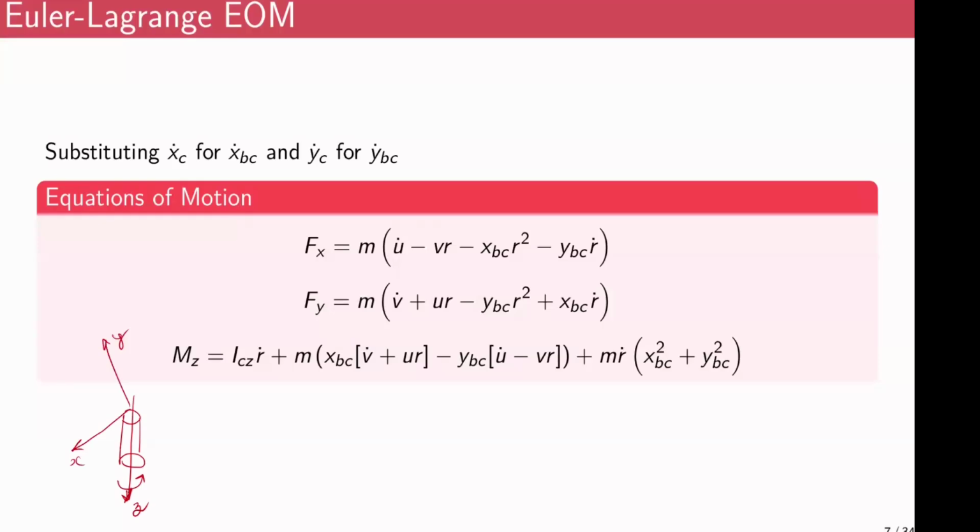You only actuate the revolute joint with respect to the z-axis, right? You only give the torque command with respect to the z-axis. So Euler-Lagrange is very good at giving you only this information. It will filter out the other reaction forces. So if you have multiple such revolute joints, Euler-Lagrange would only give you the relevant torques about the z-axis of all the other joints.